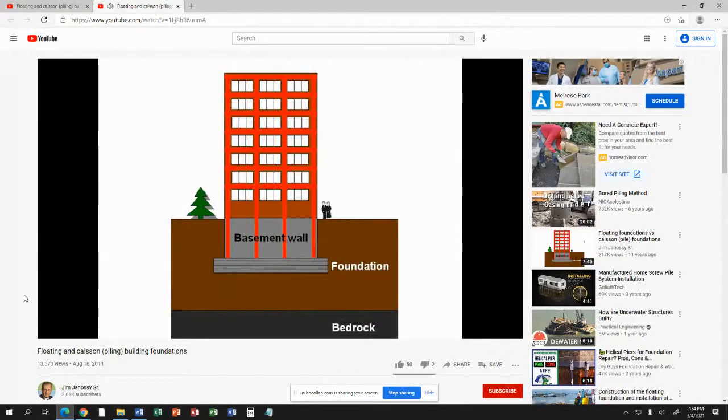Here is a kind of a cartoonish picture of a small steel frame building. The steel frame is illustrated by these red members, painted steel perhaps being used in construction. And what you see here is a typical way that early steel frame buildings were constructed. The building is held up by a foundation that consists of a kind of raft of maybe steel beams embedded in concrete or even railroad ties and railroad track, as in the Auditorium Building. And the steel members stretch all the way down to that foundation.